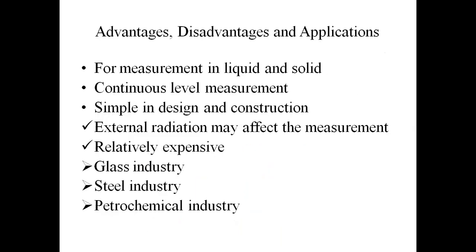Advantages, disadvantages, and applications. Advantages: it is used for measurement in liquids and solids. It is used for continuous level measurement. It is simple in design and construction. Disadvantages: external radiations may affect the measurement, and it is relatively expensive. Applications: it is used in the glass industry, steel industry, and petrochemical industry.